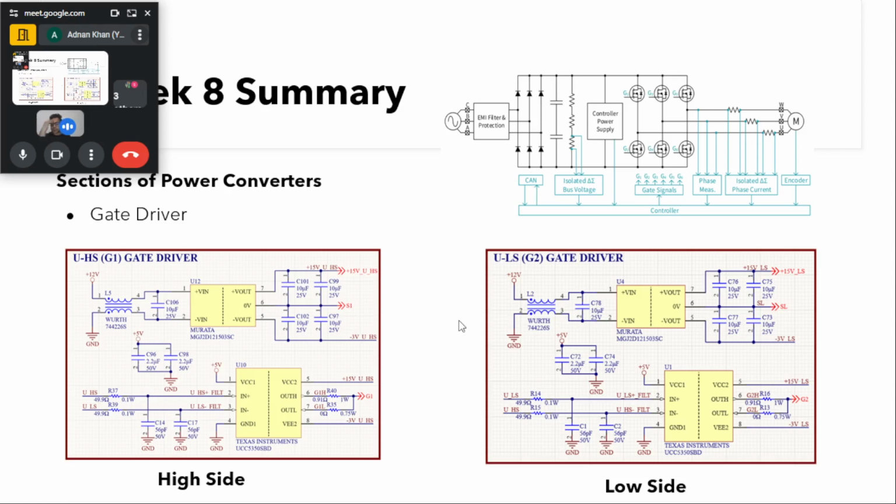For that, if you can recall, we saw in detail the gate drivers for driving the devices 2-3 sessions back. So for these high side switches we require isolated supplies, a floating supply at the source of these top side devices.